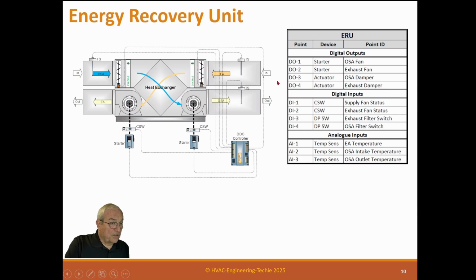If this is a prison, boy, this can fill up really quickly. And I'm not sure I know why, but I've done several jails where the exhaust airstream is just full of cotton dust and cotton fibers, and it will basically destroy this heat exchanger if you allow that fiber to get in the heat exchanger. So those filters also need to be changed when it's ready.